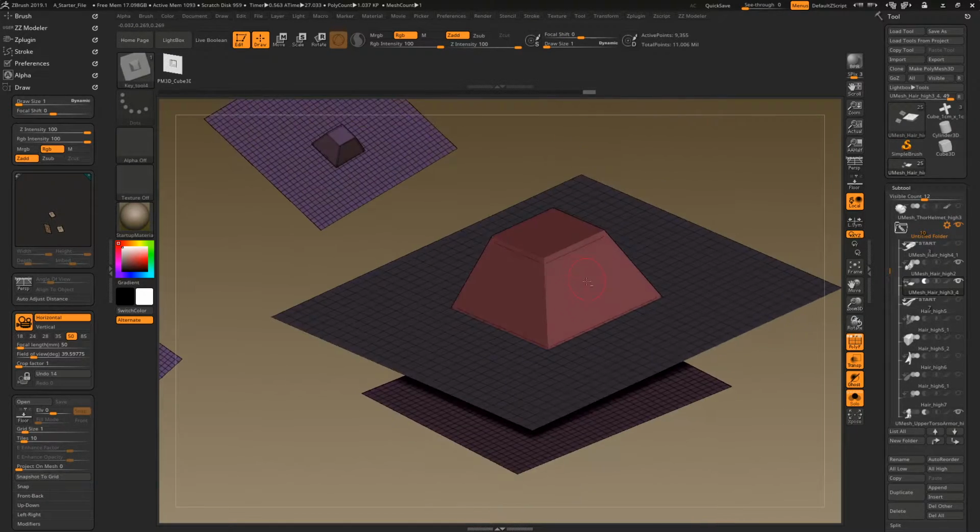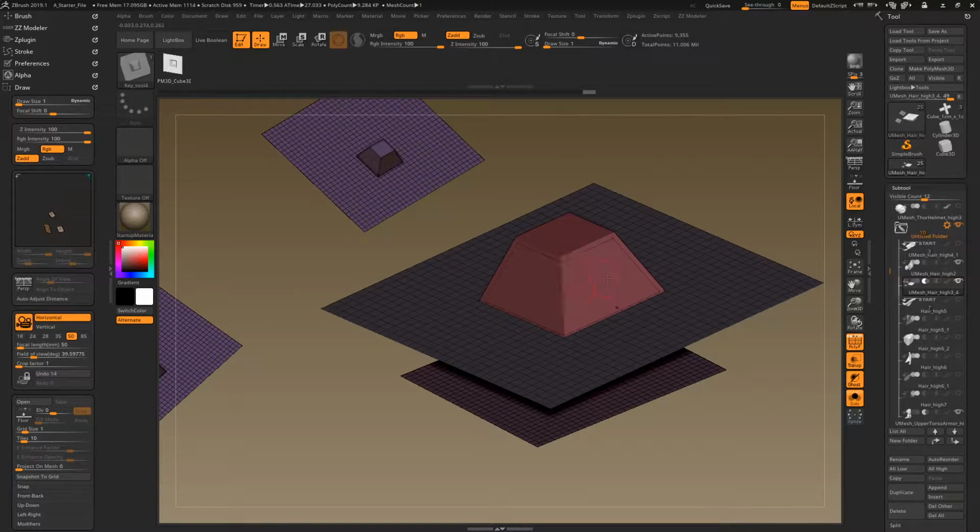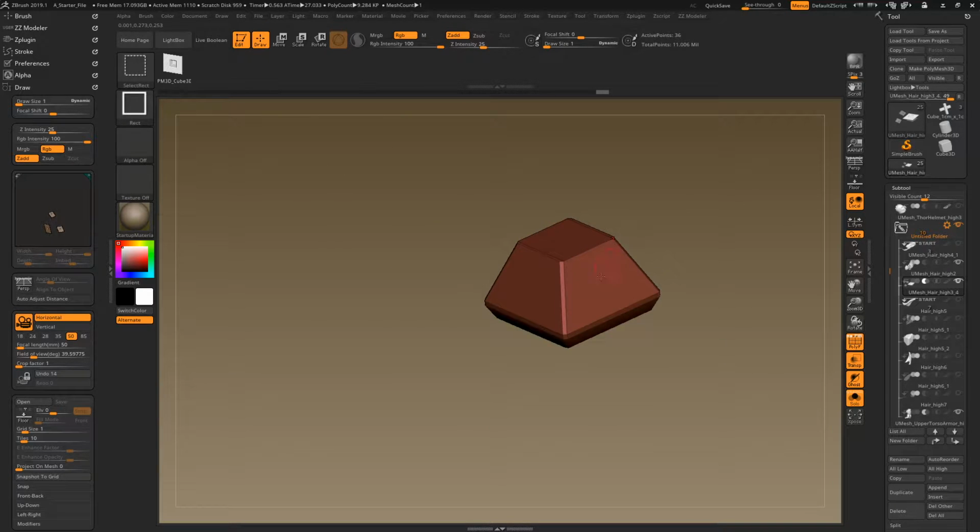And the reason for that is that you don't want it to touch. You only want these side planes to touch, and you don't want to bind in the corners, which can happen if you have what's referred to as overbake, which is a process that happens in SLA printing, where the print can swell because of too much light.